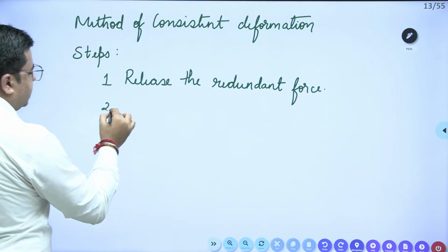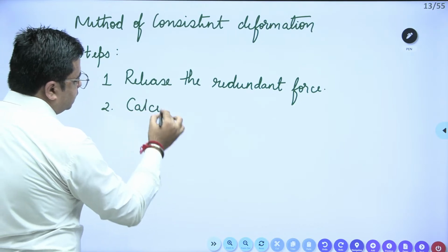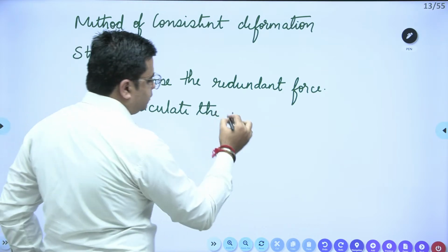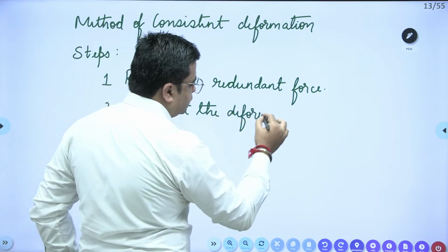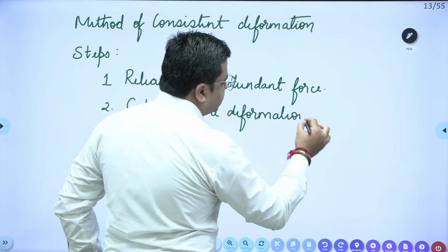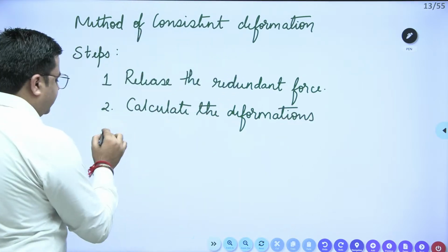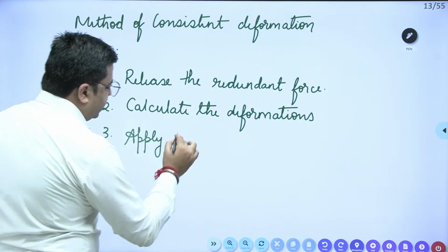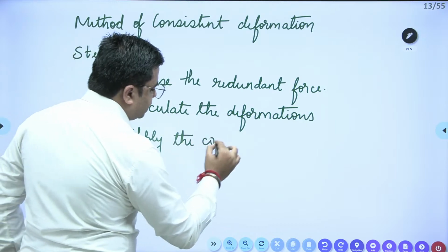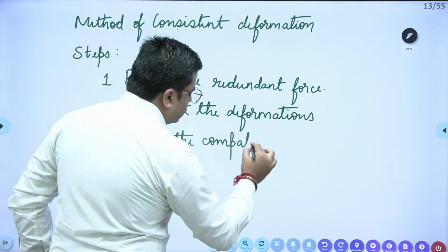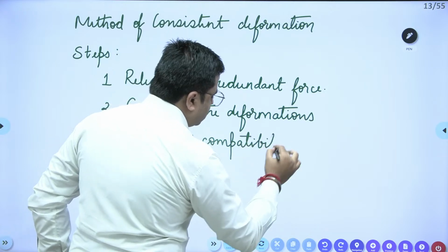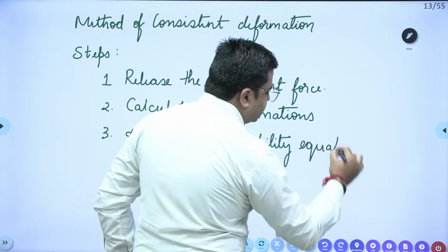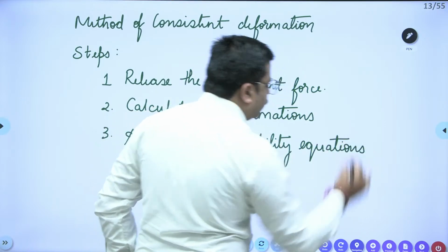Second, calculate the deformations. And third, apply the compatibility equations. So using these three steps, you can determine the unknown forces that are asked in the question.